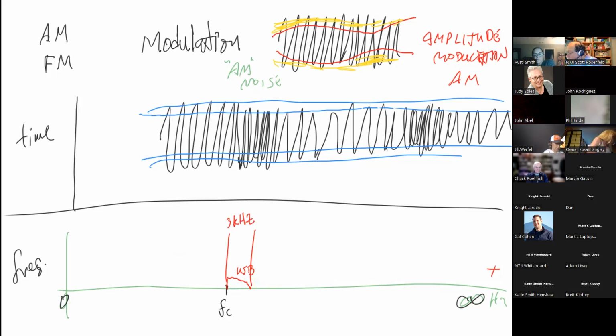Frequency modulation, the reason that we don't usually use it is because frequency modulation will fill up a space that looks between 10 and 15 kilohertz wide. This is why we use frequency modulation on higher frequencies. If we were to look at some of the lower bands, we would find that 10 to 15 kilohertz is a lot of room. However, if we go up to the 2 meter band, which is 144 to 148 megahertz, we want to rewrite that in kilohertz.